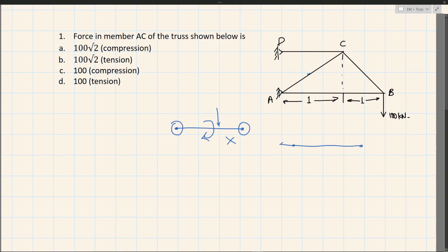internal forces of each member is only tensile or compressive, right? So this is not the external force, mind you, this would be the internal forces. Here this 100 kilonewton is the external force that is acting upon this joint B, right? Due to this external force and also the supports given to this truss, there will be internal forces generated in it. I'll not go into the theory in depth, but each member in a truss will develop some internal forces, and those internal forces will be only tensile or compressive.